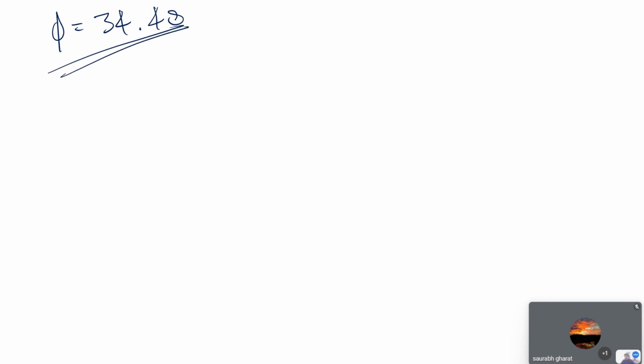So what do you need now? You know the formula of feed, because you have the depth of cut and you have the feed also. Your thickness you have. But you need to find the width, because you need to find Fs. Now we need to find out Fc and Ft. For that we go through Fs, and we can go to our Merchant circle.